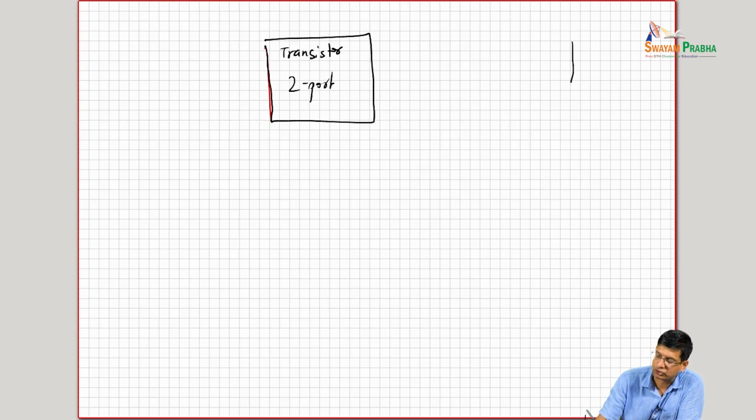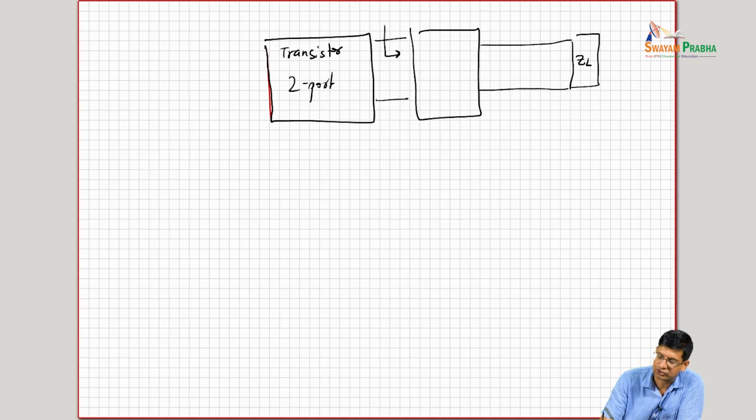There is an actual load that I'm trying to drive, right? So what I do is I build some network over here, which takes this load and makes sure that we can call this the matching network, right, which takes this ZL and moves this to the equivalent of gamma L max.